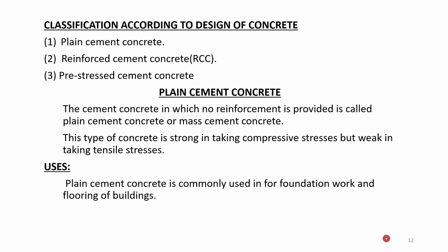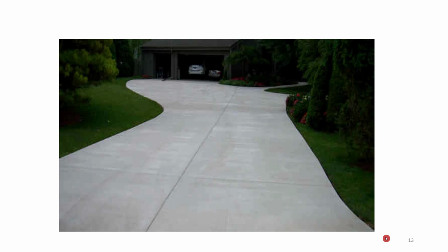So by definition, cement concrete where there is no reinforcement provided is called plain cement concrete or mass cement concrete. But they are very weak in taking tensile stresses. So it can be used only for some flooring works, because the concrete should not have any tensile stresses. As it is resting on soil, there won't be much stress happening to the concrete.